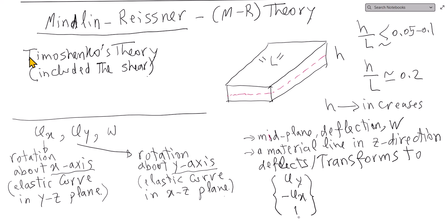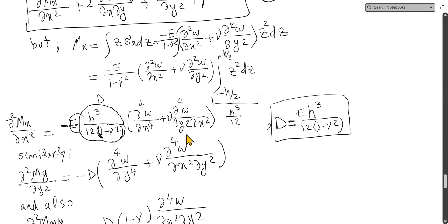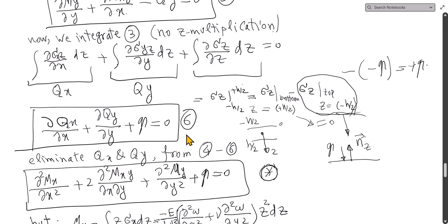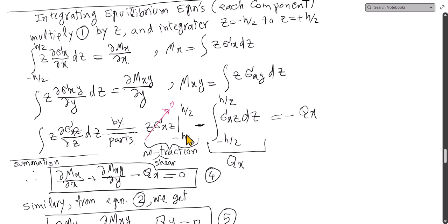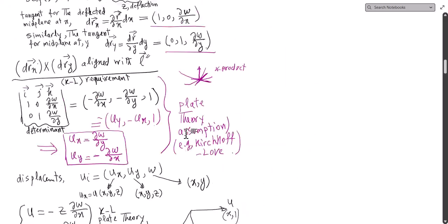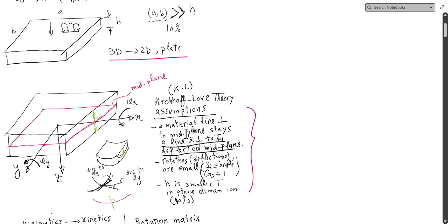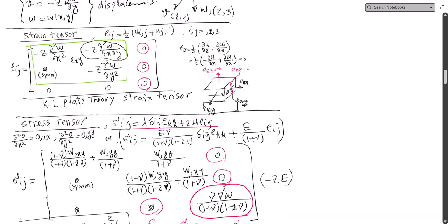If you have not seen the video on Kirchhoff theory, I would suggest that you watch that before this Mindlin. There are many concepts that we will refer to, and because of that theory, we have identified these quantities that I'm going to use. If you recall, in that theory, we said that a material line perpendicular to the midplane stays perpendicular to the deflected midplane.